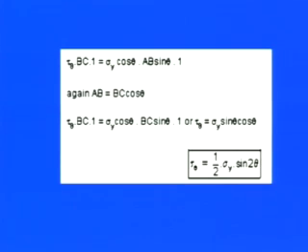There is no shear component applied, but because of the pure normal forces we have both components at the oblique plane: the normal stress component and the shear stress component, and we can easily get their values. There are no shear forces or parallel forces exerted on the different layers of the structure, but if only pure tensile or compressive forces are present along any axis, we have both components within the structure, with these values.